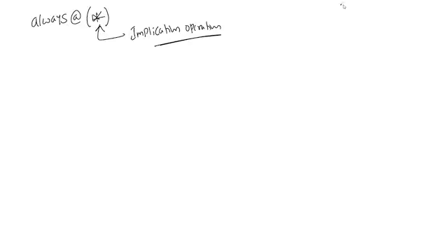Suppose you are designing a big project like some SOC or IP, so you have 150 inputs or 200 inputs. These inputs you can't declare in the sensitivity list, no? So in that situation, you can use this implication operator, that is star. Okay, so is it fine? Do you understand? Any doubts or queries?